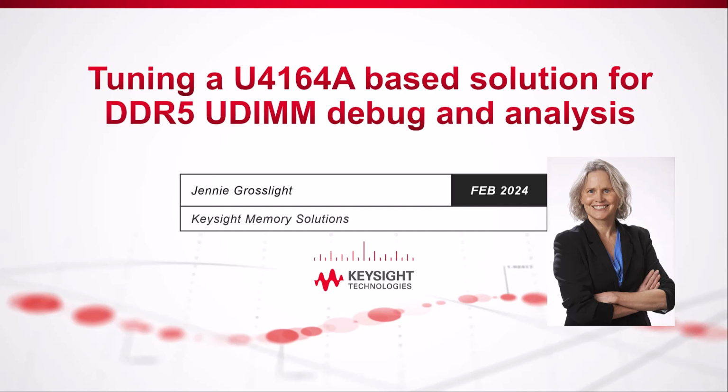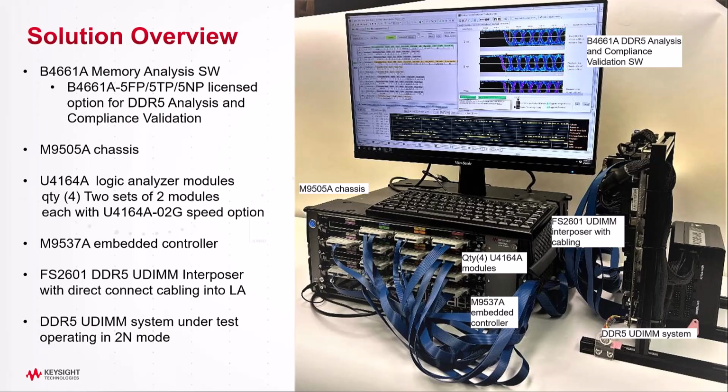This video covers tuning a U4164A logic analyzer-based solution for DDR5 UDIMM debug and analysis. This slide shows the complete solution to be able to capture all of the address command and data off of both of the DDR5 subchannels on a single UDIMM simultaneously.